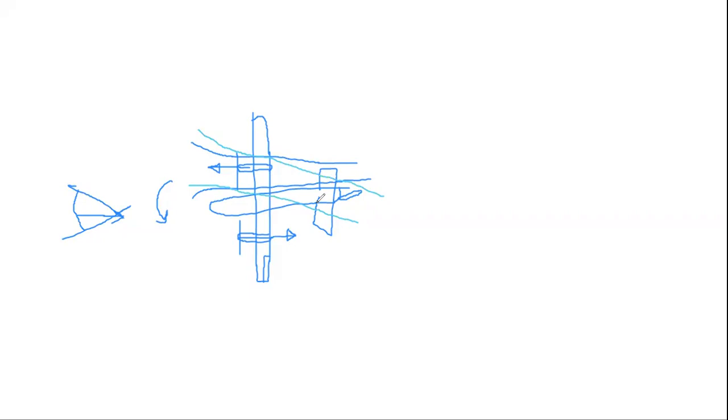And from this interaction between the propeller slipstream and the rear part of the fuselage, new forces rise, and these forces also change the moments, because there is a difference in airspeed on the fuselage in this part and in this part, and this difference of speed creates additional forces, and when the slipstream goes to the rear part of the fuselage, it raises new additional forces that tend to turn your aircraft more.